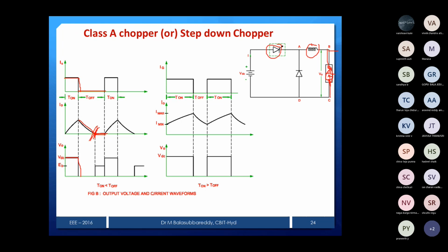Whatever the battery voltage or the back EMF voltage is. That's why I mentioned the 0 point here, because the diode is turned on. When is the diode going to be turned off? Whenever the energy stored in the inductor is completely dissipated, no current passes through the diode, and automatically the diode will be open. Very simple logic.